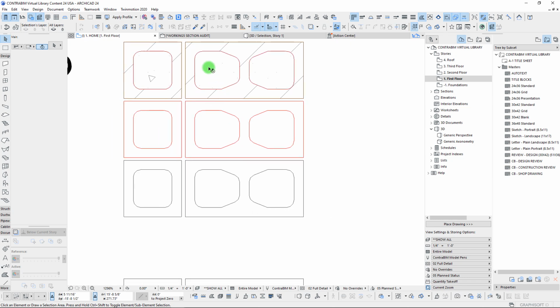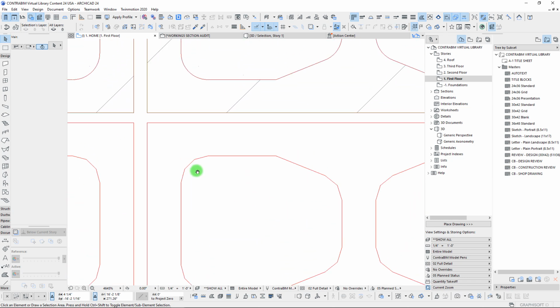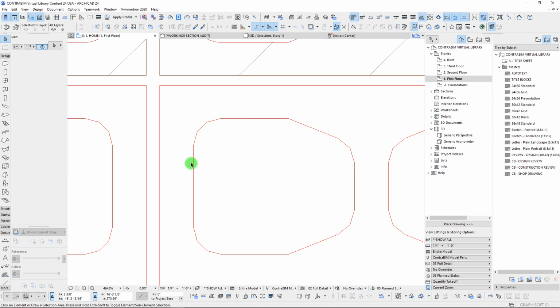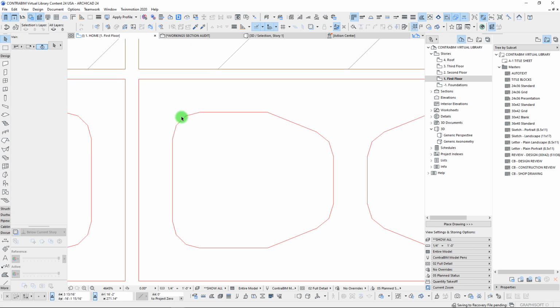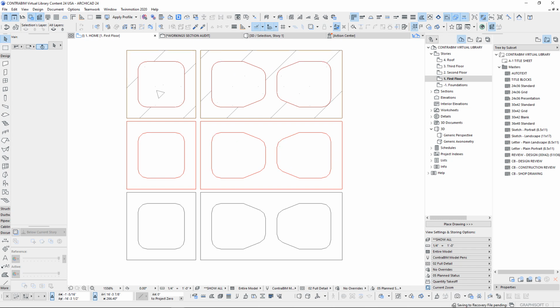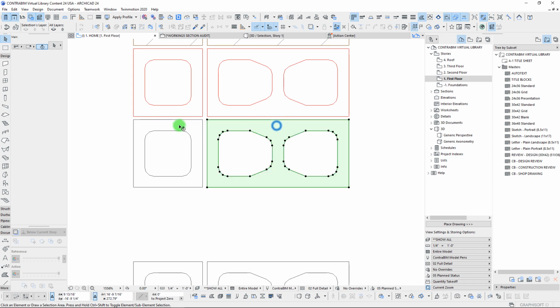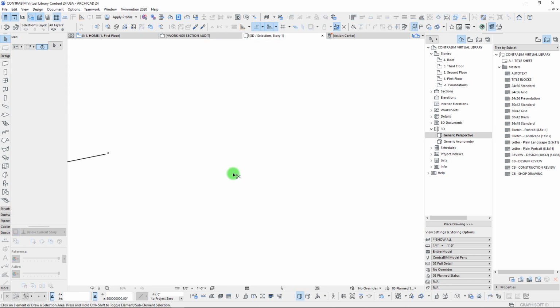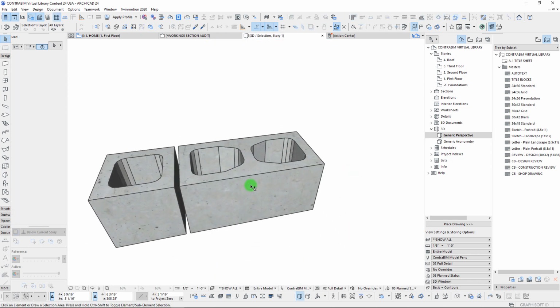Quick note, when creating these types of panels, it is good to limit the radiuses on these. If we stuck with this pure radius, then we could end up with way too many polygon counts later on. So I did break this up a little bit so that we only have 3 on that radius and 2 over on this one. It looks about the same when you look at it in plan view here. From there, I essentially just saved these off as some slabs, as you can see in this case. So there we go. We just have our 2 different blocks.